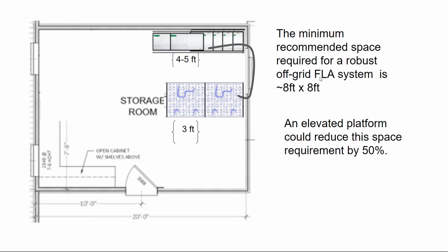And so what that means is, it's not that you can't have this stuff far away from each other, but you don't want to get excessively far away. So maybe the best battery layout for flooded lead acid is, again, where you have the short end up against the wall, but the long end sticking out from the wall so that you can actually go and service all these little terminals as needed.